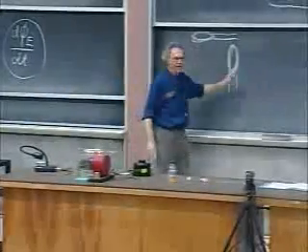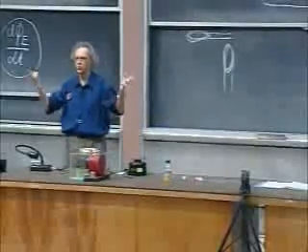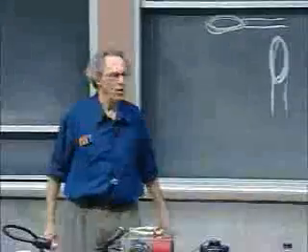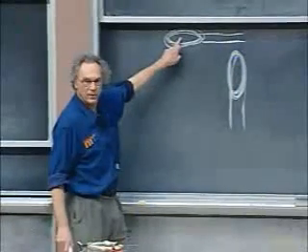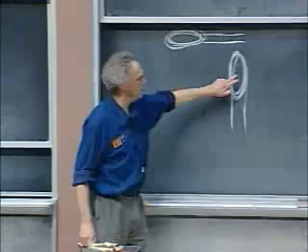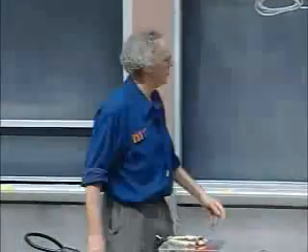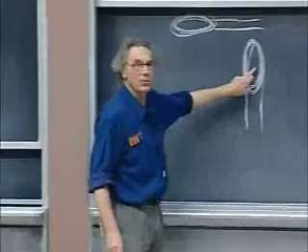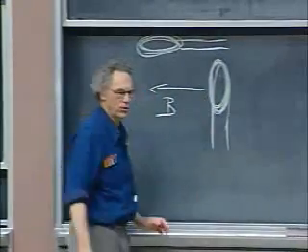These two currents are 90 degrees out of phase. Not 120, but 90. So it's a two-phase current. So when the current is maximum through this one, it is zero through this one. When it is maximum through this one, it's zero through this one. Let's look at the moment that the current is maximum through this one. And let's say the magnetic field is in this direction, which is created by this coil.